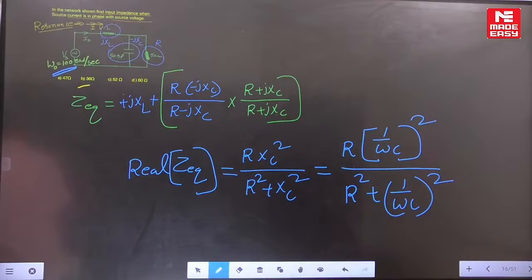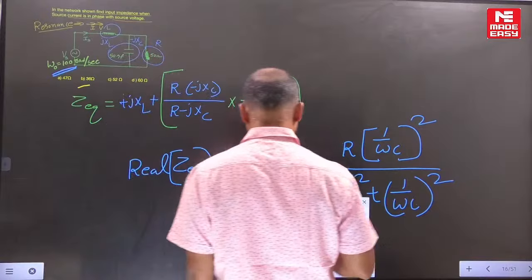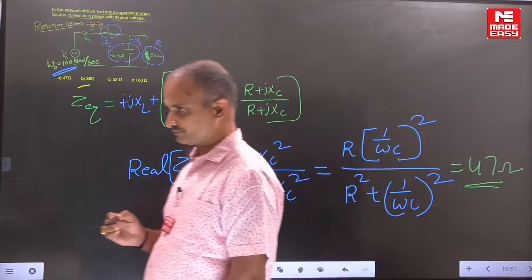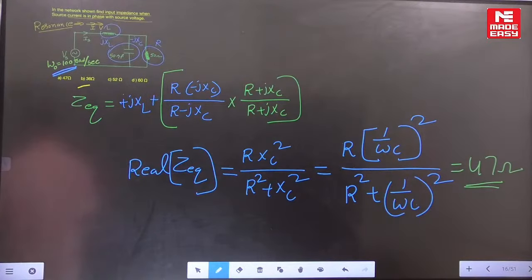Anybody answers? At resonance condition, the imaginary part of the impedance equals 0. Thereby only the real part is present. From that you conclude the answer. Substitute the R value, omega value, C value. Check karo. Many students are saying the answer is 47. Is it correct? Check karo ji. I am writing your answers only. Is it correct?